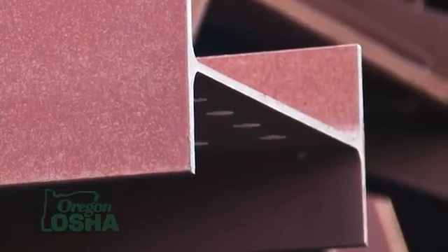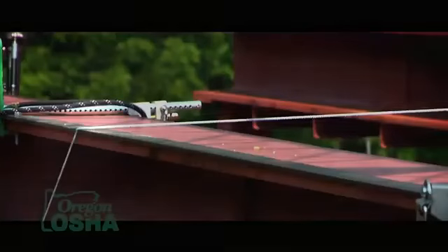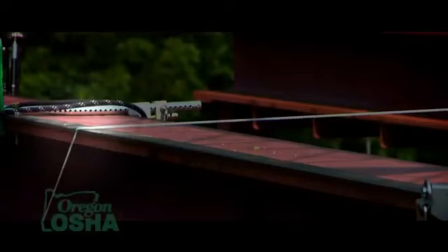And there are some definite hazards there when people are working on leading edges that are sharp and don't have the proper equipment or don't have their systems properly put in place. We have the hazard of cutting the lifeline, definitely, whether it's web or cable. We do have cut hazards that are there. There's also, as we said earlier, the clearance hazards that go along with that as well.